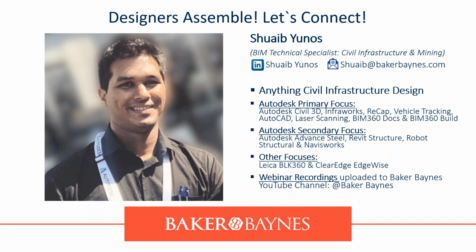Alternatively, I'm not sure if any of my webinars have shown it, but it's very, very straightforward. Just make sure that your final surface is defined in Civil 3D, and once you save it, import your Civil 3D surface into InfraWorks. Make sure it's coordinated or geolocated correctly, and it will update to reflect your final ground or your final design.